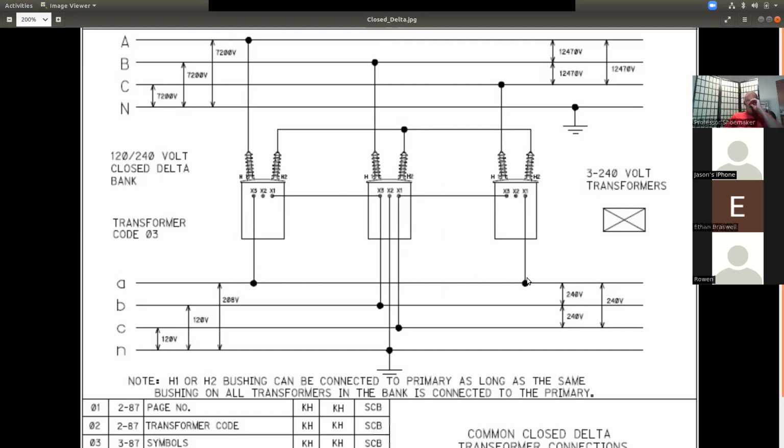Open delta, to give you a little description here, I gave you Oliver's before as an open delta situation. Most of the inside is just lights. I think he uses electric grills in there. That's 120, 240. And that AC unit was the only thing three-phase he had running in the place. And it's a real big unit. So a little bit of three-phase, a lot of single-phase power that he needed.